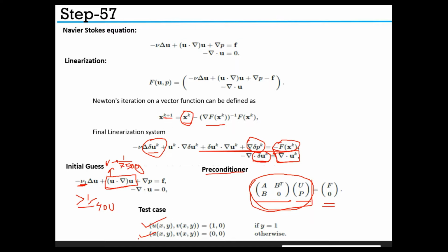When we solve this problem, the error consists of nonlinear error and discretization error. The nonlinear part decreases with each Newton iteration, and the discretization error reduces with mesh refinement. In this example, the solution from the coarse mesh is transferred to successively finer meshes and used as the initial guess. Therefore the nonlinear error is always brought below the tolerance of Newton's iteration, and the discretization error is reduced with each mesh refinement.